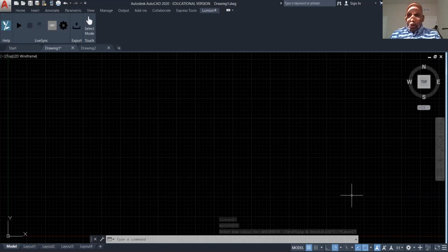Okay, those are some of the basics. Over here, this is your user coordinate system. Where the x-axis meets the y-axis, that's absolute coordinate 0, 0. As we locate objects within our model space environment, they're going to be relative to their position against absolute coordinate 0, 0, right here.